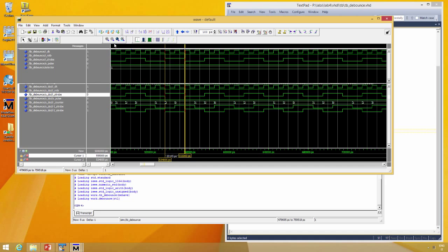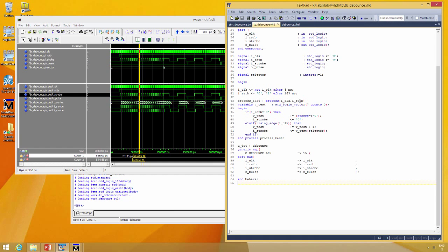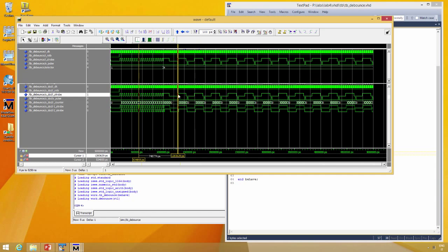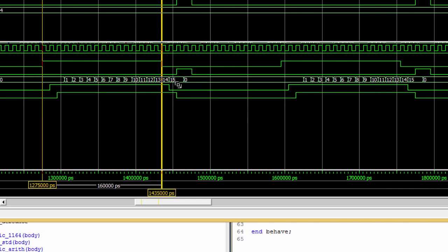No output pulse is generated. Because our debounce logic filters all the strobes shorter than 15 clock cycles. In this case, the input strobe is 17 clock cycles. In fact, the debounce logic generates a pulse.